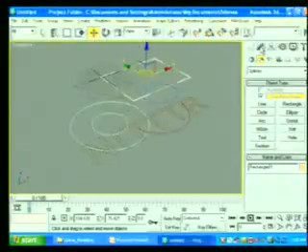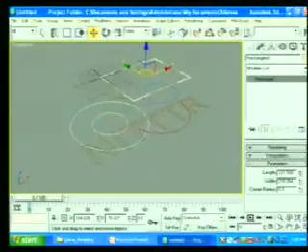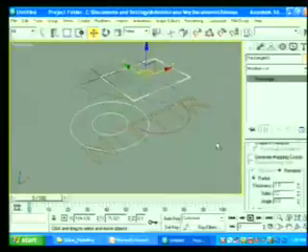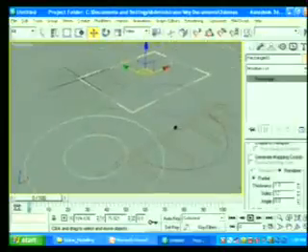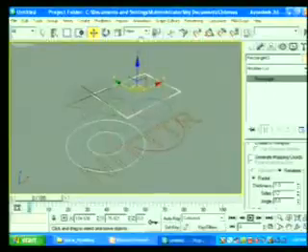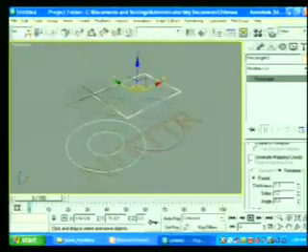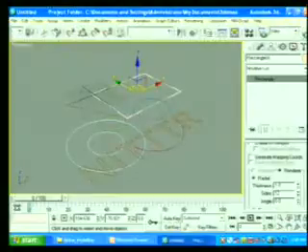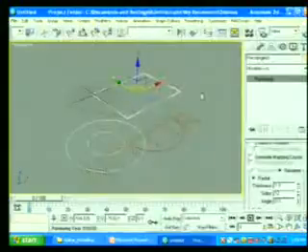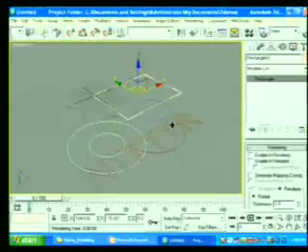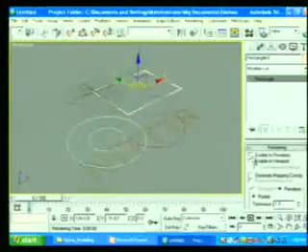If we select the rectangle and go to the modify panel, as I have told you before, every object has properties which come under the modify panel. Rendering: if we press F9, we can't see it in render. We just see it in the viewport only. If we mark here enable in render, you can see it in the render.